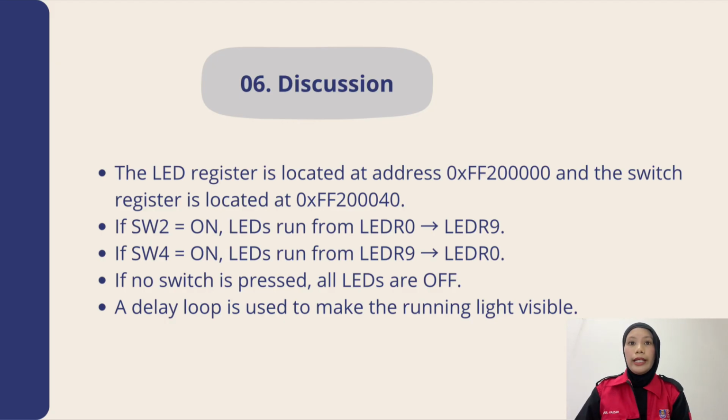So next, when switch 4 is pressed, the program executes the LSR operation. The running light moves from LED 9 to LED 0, producing a right-shifting running light effect.